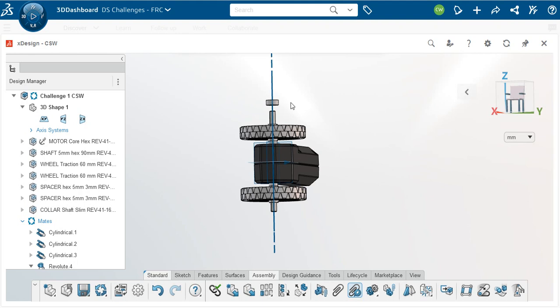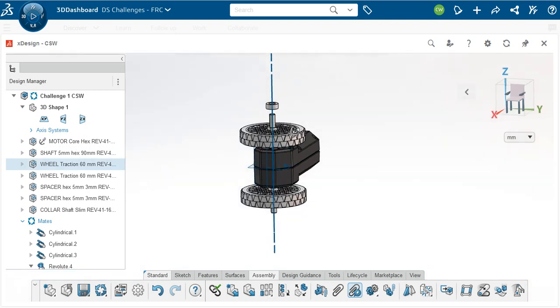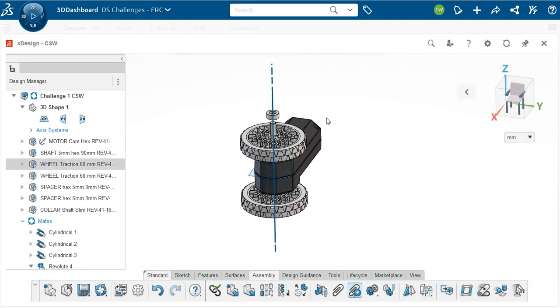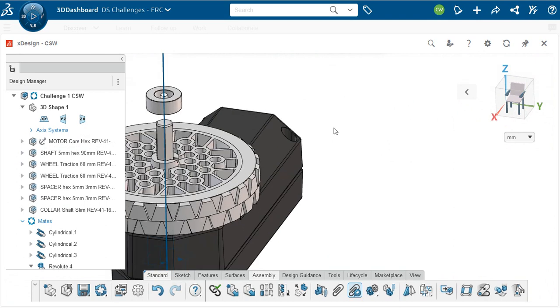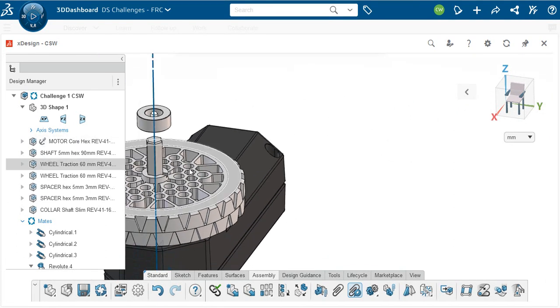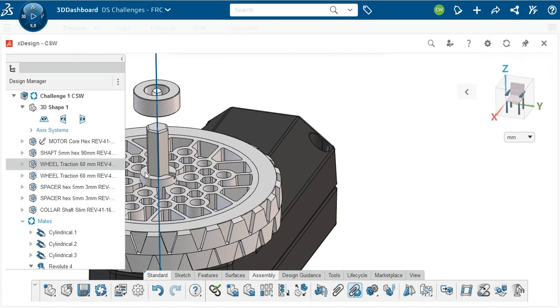Okay, now where do I want the shaft collar to sit? I could sit it at the end of the shaft, way out here, but then that doesn't keep the motor pushed up against anything. So what I'd like to do is I would like to mechanically have the shaft collar rest against this face. Let me bring that face in. This face of the wheel. So it snugly, not tightly, not over tight, but just snugly does it. So let's see if we can do that.